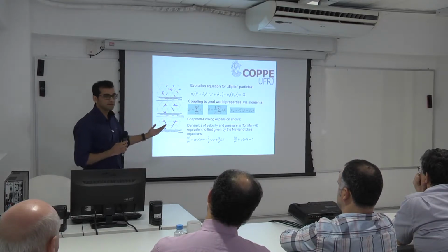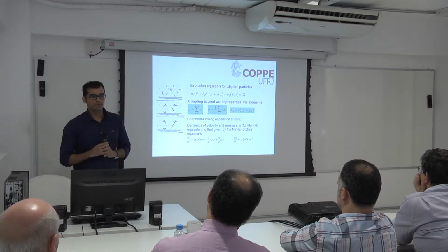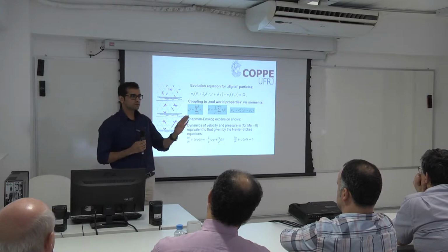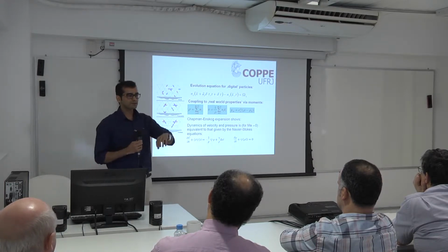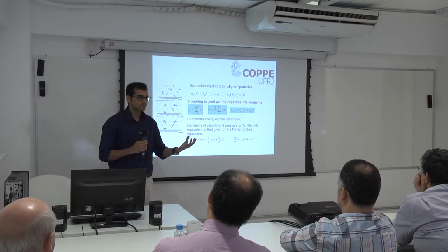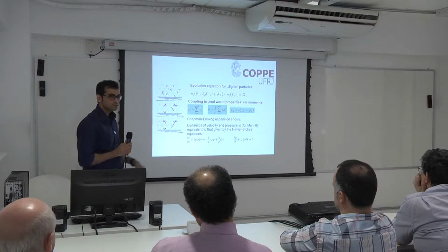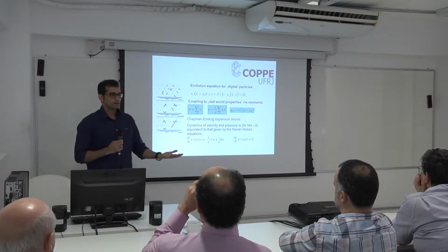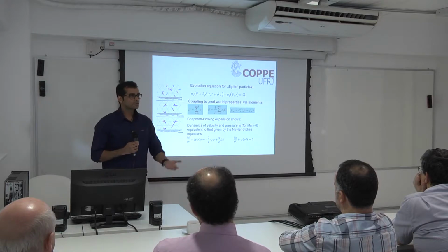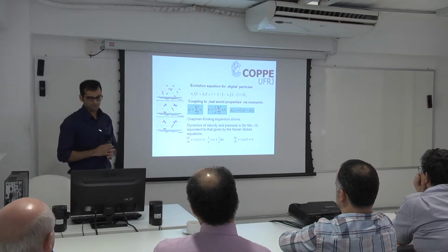So Lattice-Boltzmann uses a different approach. It uses a bottom-up approach. It approaches the solution of Navier-Stokes by already implementing the solutions it had. So this is the key point. And so what happens with the pressure? Pressure is simply calculated from the equation of state. You don't need the Poisson equation anymore to solve for the pressure in Lattice-Boltzmann.